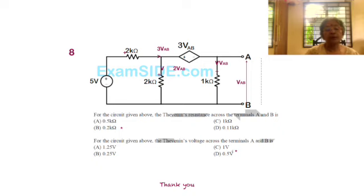We know what VAB is, and this VAB is also the voltage across the 1 kilo ohm. So if VAB is the voltage across 1 kilo ohm, the current is given by VAB divided by 1 kilo ohm, or VAB milliamps. Milliamps is not shown, that's all. So the current and the voltage have the same magnitudes, one in volts, the other in milliamps.